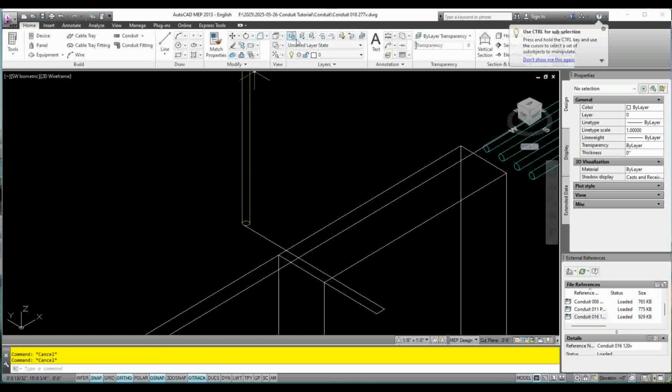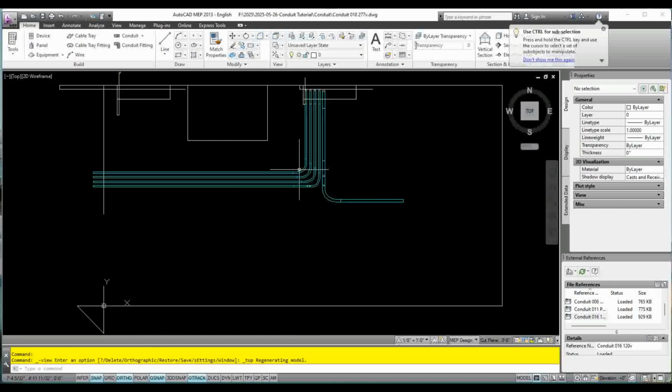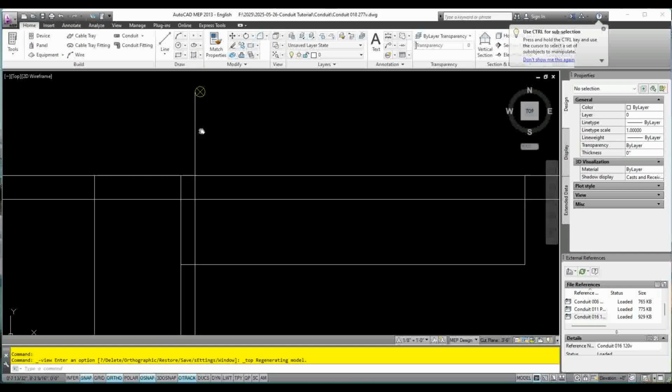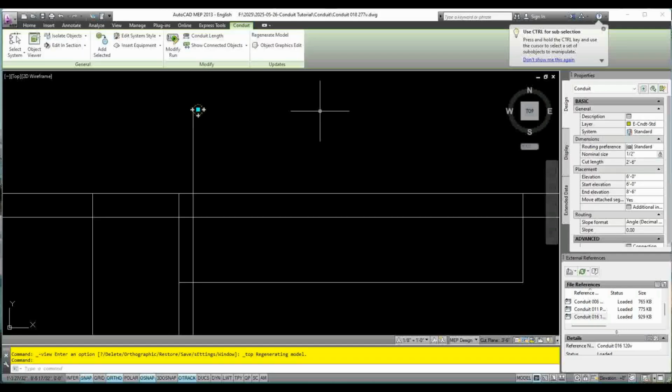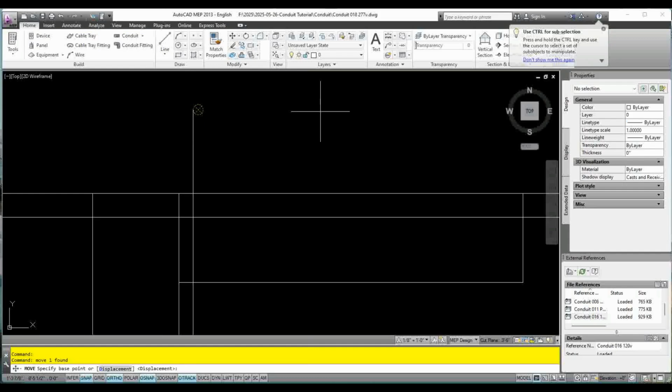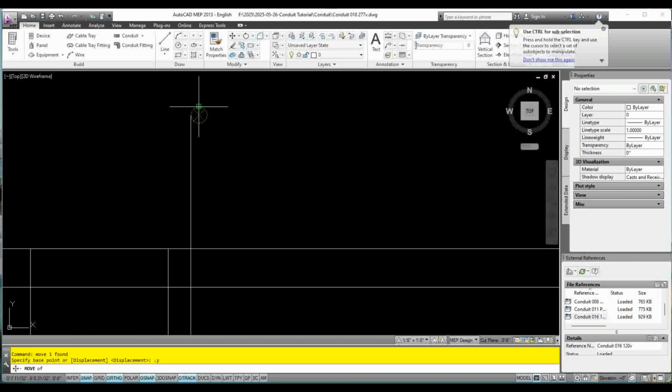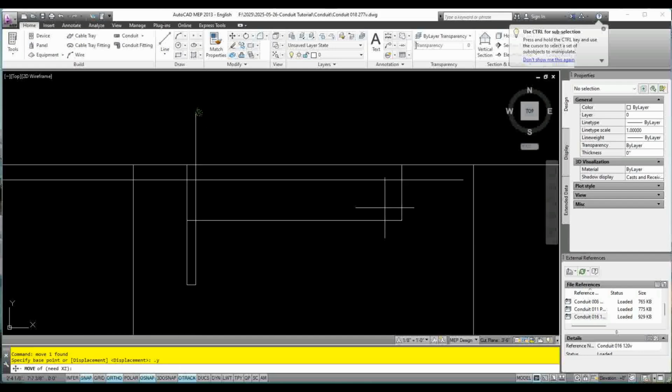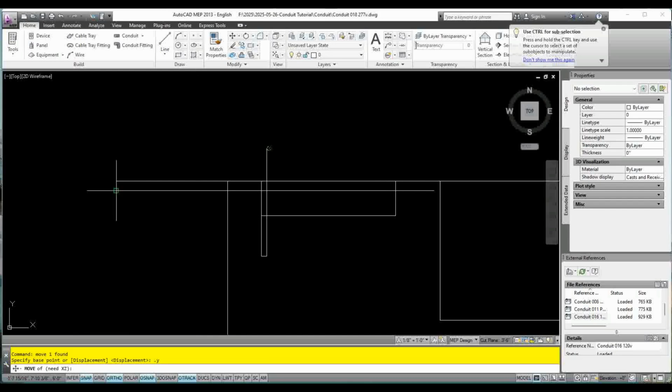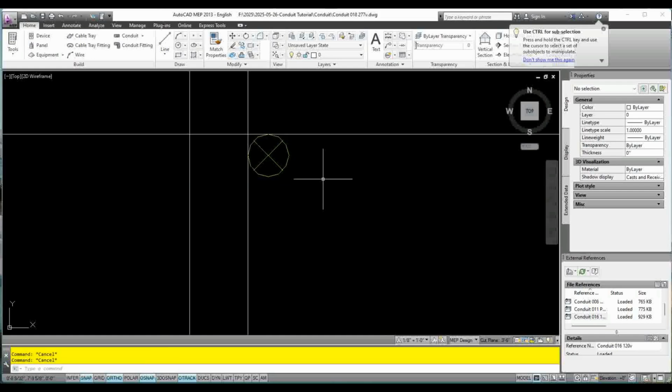All right, so let's go to the, everybody come up here to your views and go to a top view. All right, now we're going to look down on this pipe. Highlight it, click on it, move, enter, and we're going to move it in the Y direction. Dot Y, enter, all right, and dot Y of what? Of that point, and where's the strut? Okay, the face of the strut is right here, right? There we go. Click once, click twice, escape, escape, escape, and look at that.